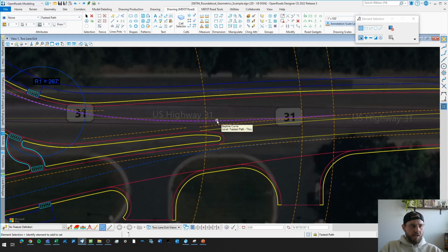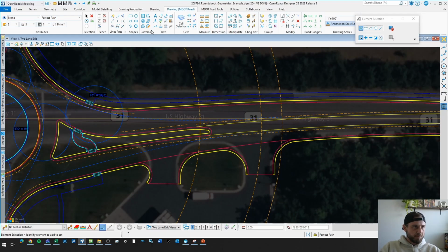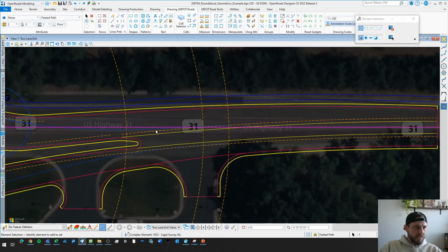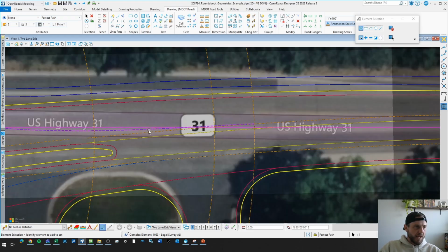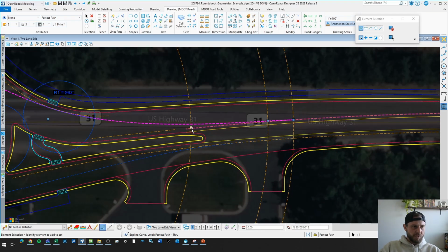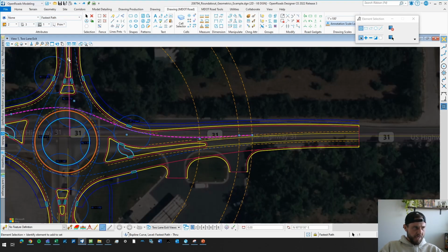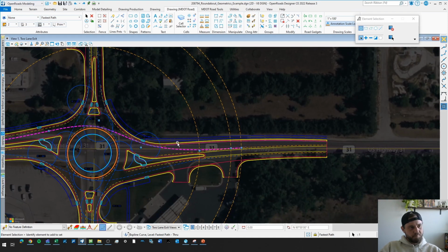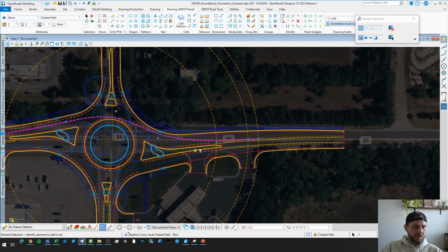I'll trace in on this one. And this is just created using this B-spline. If I can find it right here, this B-spline by points. The first 2 points I select on the intersection of that line for my outer edges, and then after that, these 3 points can change to figure out where that tightest radius is.